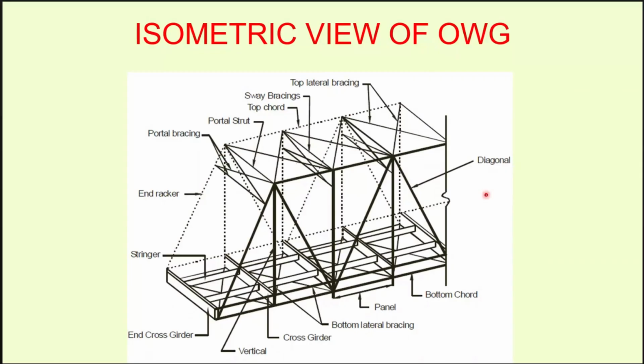Again, in this you have to understand that the top chord will be under compression, and the bottom chord will be under tension. This member is also typically under compression. So in a truss you can say this will be totally under tension, whereas everything here is under compression.